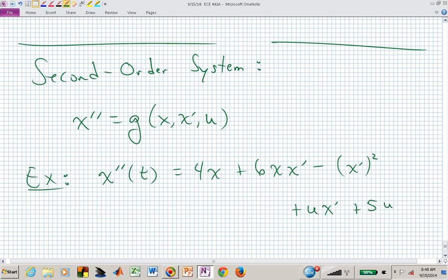First thing you want to ask is, is that linear or nonlinear? Do I even need to linearize it? If it's a linear equation, I can just put it into matrix form or just deal with it the way it is. If I wanted to find a transfer function, I could Laplace transform a linear equation and go. If it's not linear, I can't Laplace transform. Is this system linear or nonlinear? It's nonlinear all over the place, isn't it?